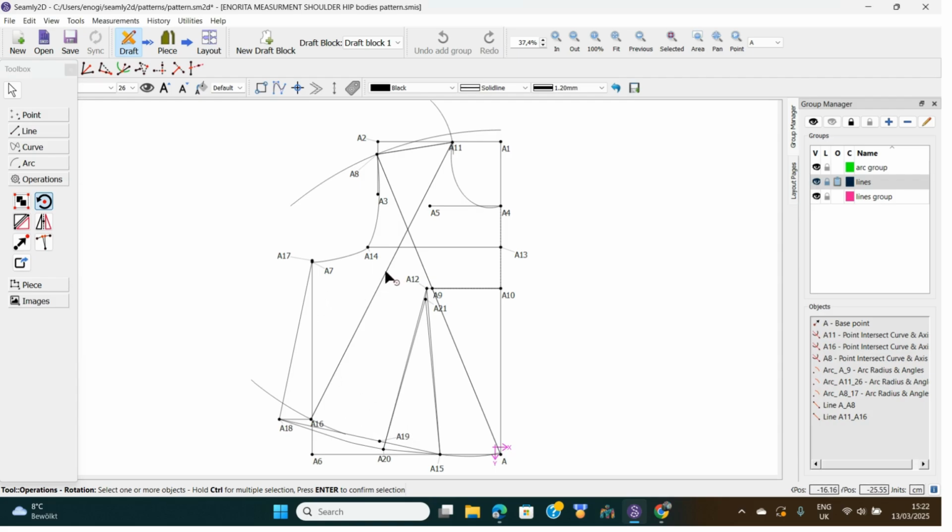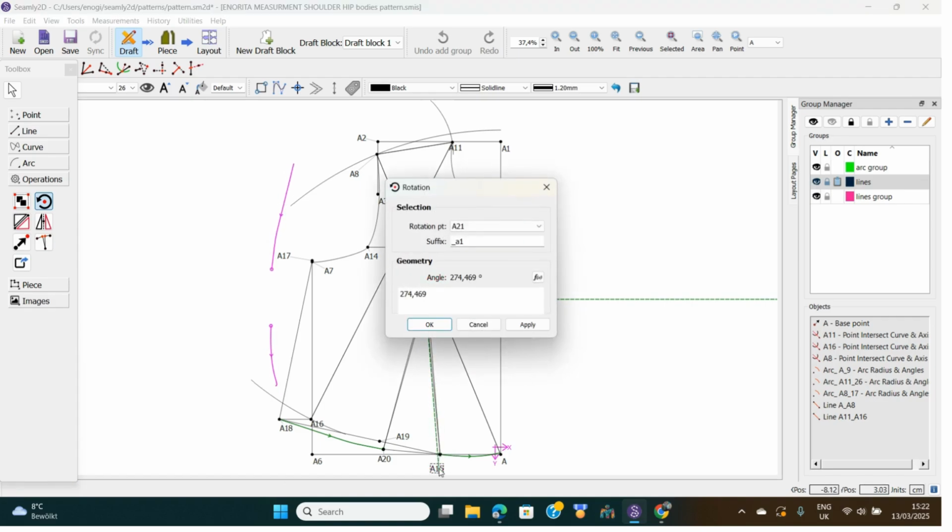So what I will do, I will just highlight it, press enter, and then look for the point I'm going to use as my axis for rotating. Let's say I want to use this point. So you see, I can rotate it to where I want. Let's say I want it to be around here, maybe around there. Then I can come down and click right there.